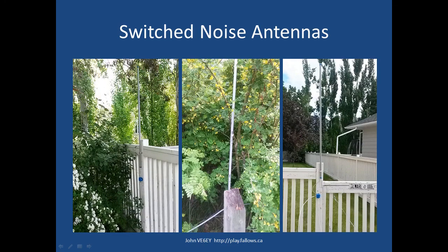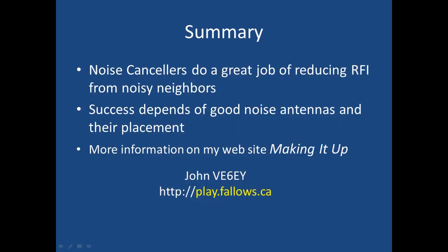And here they are. I've got 3 of them actually mounted in 3 locations, and each one is switched when it comes into my shack. So I can select which noise antenna for which neighboring house, and it works just great. So, in summary, noise cancelers do a great job of reducing RFI from noisy neighbors. Their success depends on good noise antennas and their placement.